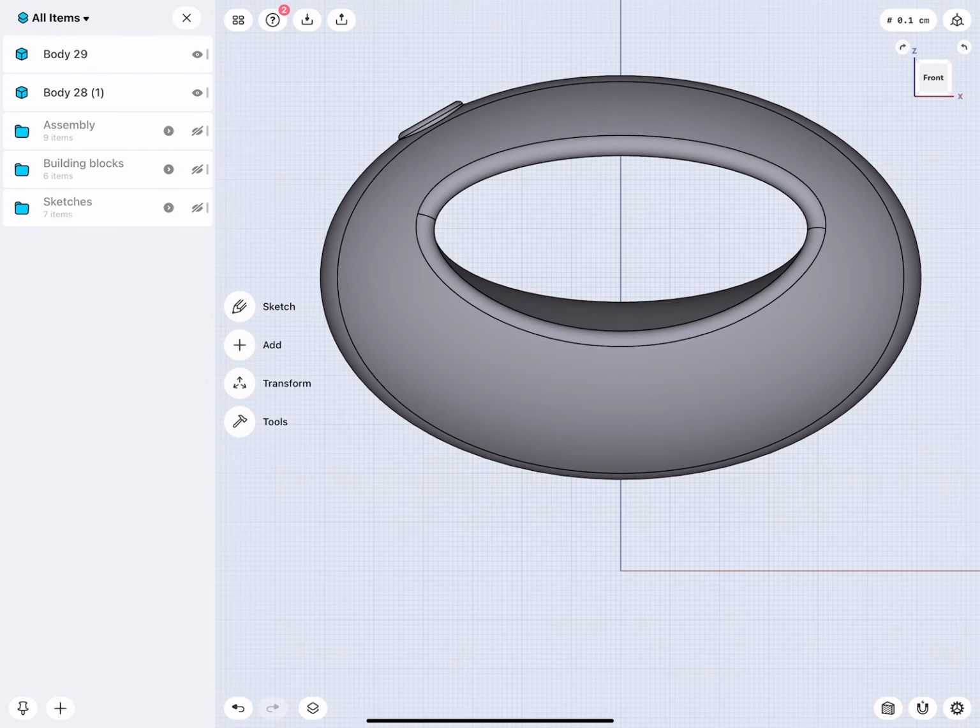So the lower section has the vibration motor in. The upper section, that is where we hold it. And we don't necessarily want the vibrations to go right into our hand. So we want to isolate, or insulate actually, the upper area from the lower area. And we could do this by having, left and right, kind of like a joint, a filler, ideally out of silicone, because it's not stiff. It absorbs a lot of the vibrations.